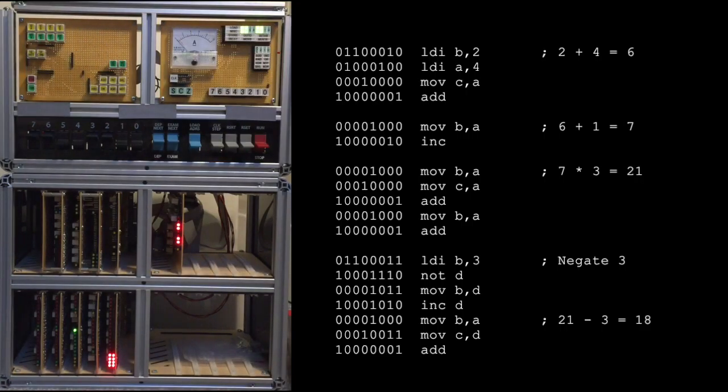What I've done there is hold down the Select DS button to get the switches onto the data bus, then tap the Load Instruction Register button. That's a bit fiddly and I'll need to do this once for each line of the program, so instead I've hacked the Deposit Next button so that it'll automate these two actions.